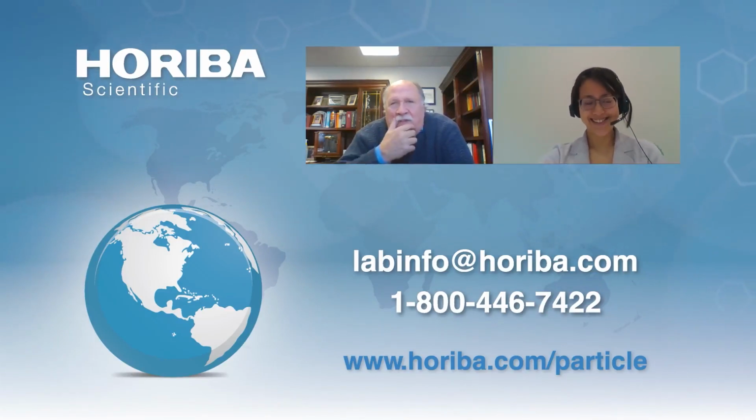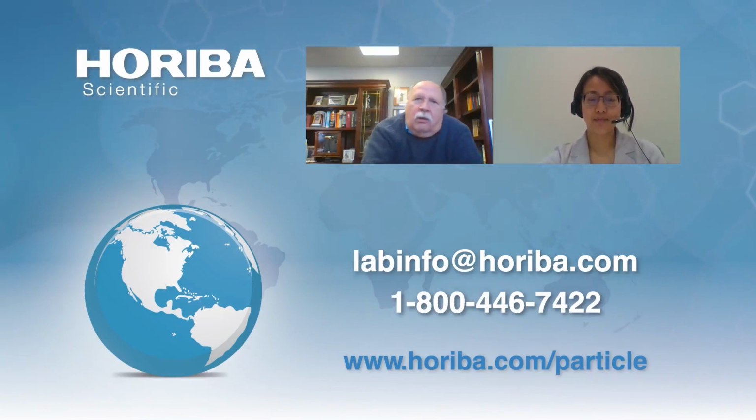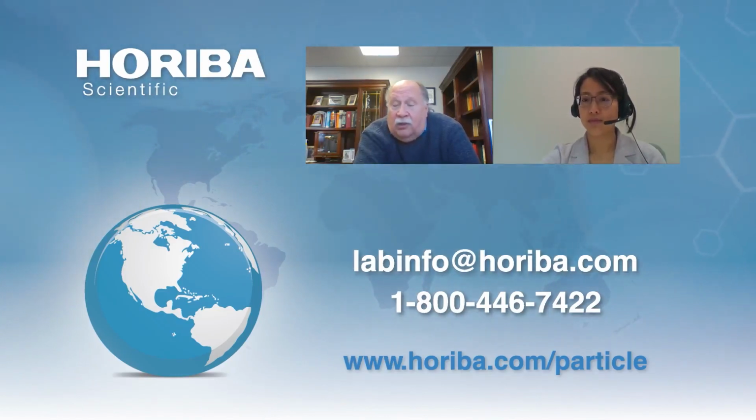One of the things that people see as a limit to grinding, Wolfgang Peukert and others have really studied this effect quite a bit. As you grind down, if you're not stabilizing that surface, you reach a point called the limit of grinding, and you just can't seem to grind any farther because you're grinding and agglomerating at the same time.